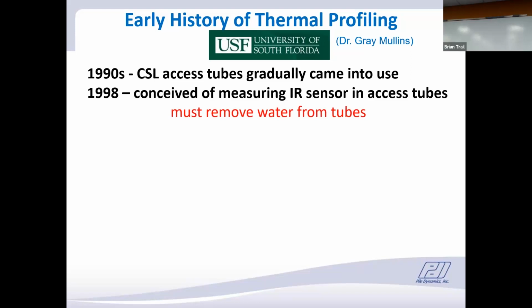For the thermal test, there cannot be water in the tubes. So we have to remove the water. That's relatively simple to do if we have, let's say, a 40-foot long pile. But now start getting an 80-foot pile, 120-foot pile, 200-foot pile, these drill shafts oftentimes are. And that becomes pretty difficult.